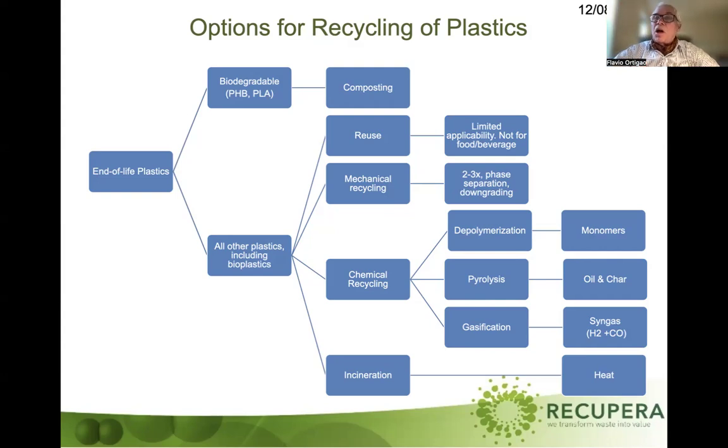You end up with oil fractions, which are all the polymers that become small enough, around 20 carbons or so. They become liquid, and you form the oil. This is the pyrolysis oil. But pyrolysis oil contains all the possible forms and branches of the original plastic, and all the contaminants, in liquid form. It's very difficult to separate. So most of the projects with pyrolysis oil end up burning the oil in a furnace.